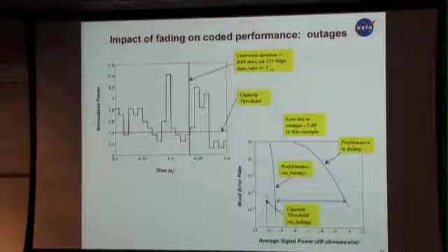What effect does a block fading model have on performance? Well, it causes outages. Typically, fades last for a long time relative to the length of a code word, so a code word isn't going to be able to average over many fades. Here's a picture: a code word lasting 0.06 milliseconds is the gap between the left and right of these blue lines.